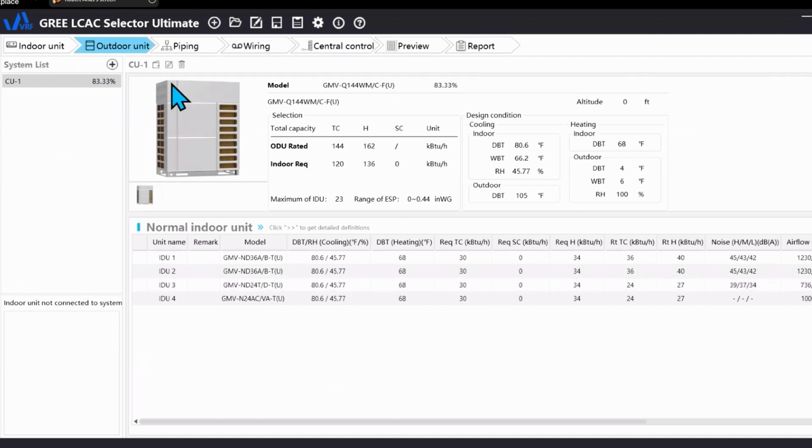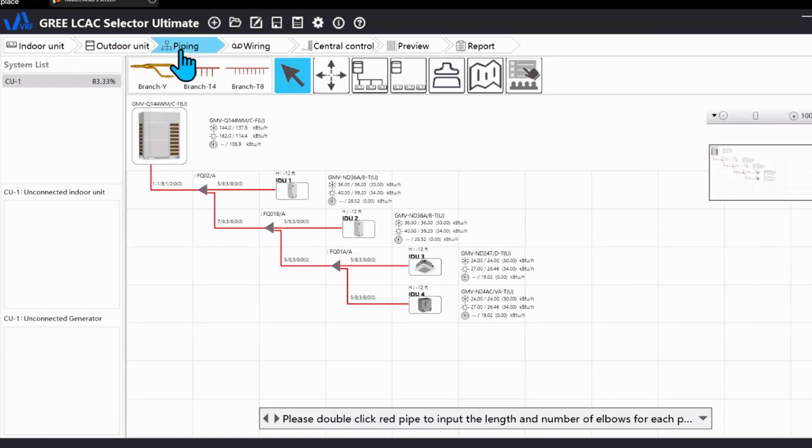The next one we go to is going to be our piping. When you select the piping, you notice the system automatically defaults to include Ys. The reason it's showing the Y like this, as Greg demonstrated earlier today, is you don't stick the thumb up. It's only doing this to show you the illustration that that's a Y, because if it was that way, it would be difficult to see. If you don't like this configuration, you can change it.